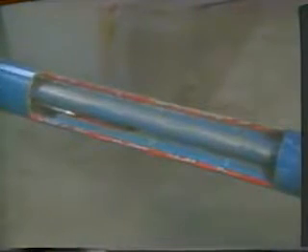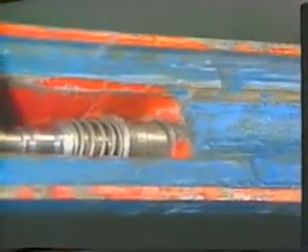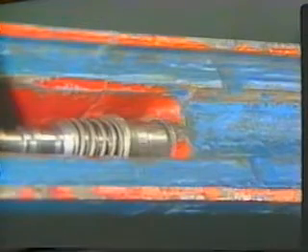Because the side pocket is offset from the center line of the tubing, it is necessary to devise a wireline tool string that can kick over into the offset of the mandrel when controls must be run or retrieved. This is accomplished by using a device called a kickover tool. There are various designs for these kickover tools. Some require that special changes be made in the side pocket mandrels in which they're run. The main thing to remember is that not all kickover tools will work in all side pocket mandrels.